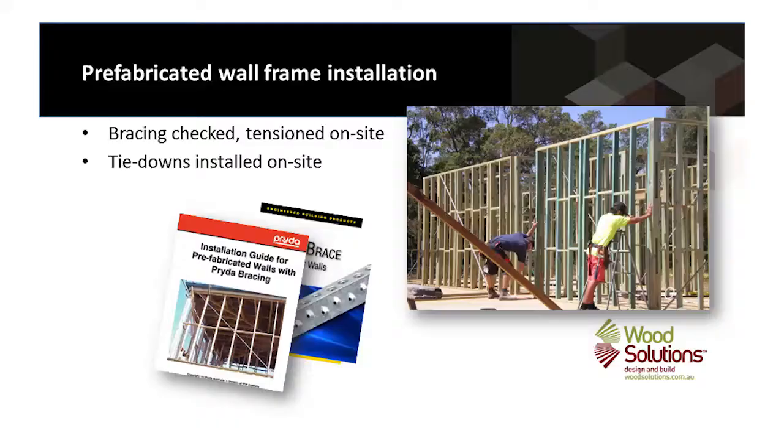They are designed in accordance with AS 1684, and exactly the same compliance documentation for the design method applies to wall frames as well. Again, with wall frames, sometimes the bracing may be on the prefabricated wall frames, other times it's erected on site, but again, in inspection, we need to make sure that the bracing is all there.